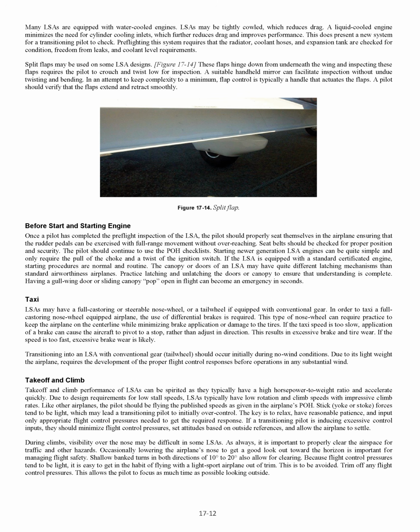Takeoff and climb performance of LSAs can be spirited, as they typically have a high horsepower to weight ratio and accelerate quickly. Due to design requirements for low stall speeds, LSAs typically have low rotation and climb speeds with impressive climb rates. Like other airplanes, the pilot should be flying the published speeds as given in the airplane's POH.